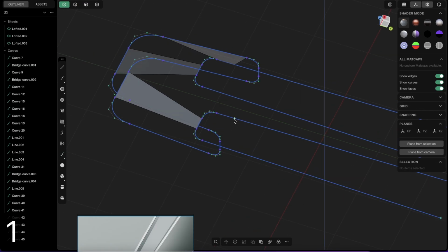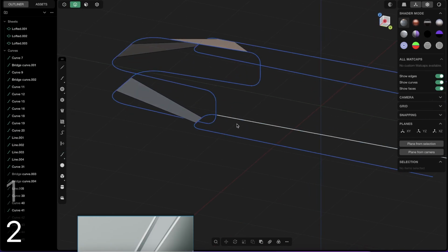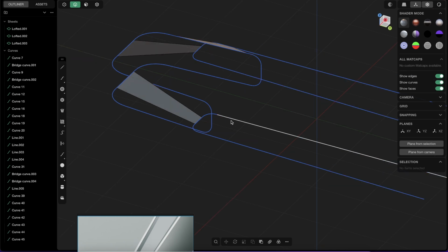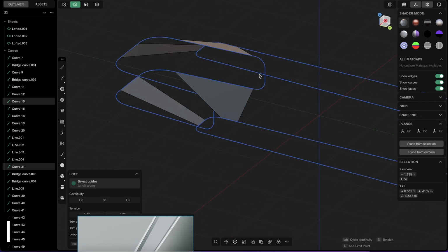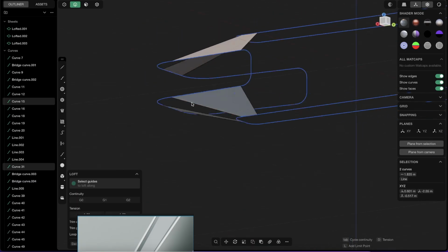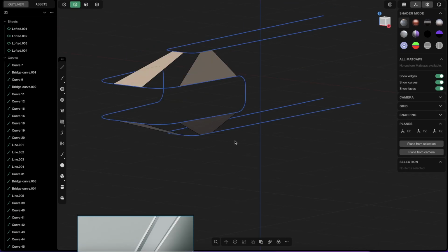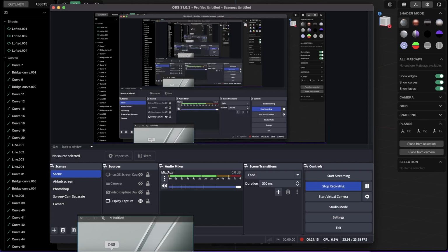And if you press 1, then you see the point is here. But if you press 2 in edge mode, you see it's still one long line. So just select it in edge mode and press Alt J to unjoin, because now you have two separate lines. And now you can again just take those lines and press L. And again, we have our flat surfaces. Beautiful. So everything comes nicely together.